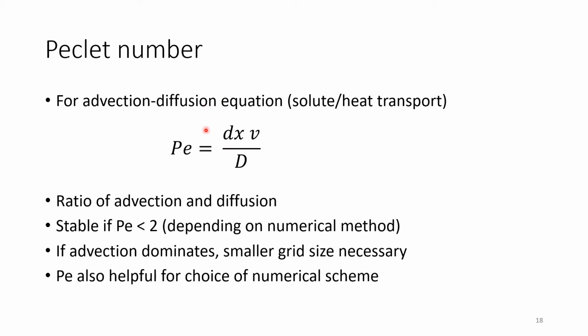So the proper value here is that the Peclet number should be smaller than 2. This kind of depends on the numerical method used, but remember for your head, because most of the simulations you will do will be finite elements based, and so you have your Peclet number of around smaller than 2 as a value to orient yourself. And this is for transport processes, especially for the advective diffusive process, which we usually have when we talk about solute transport.